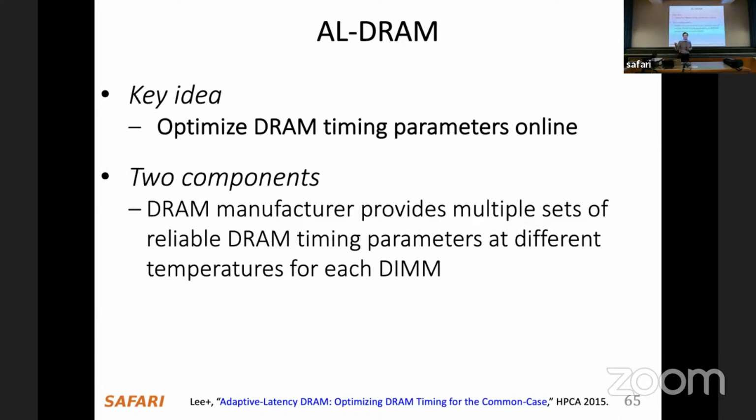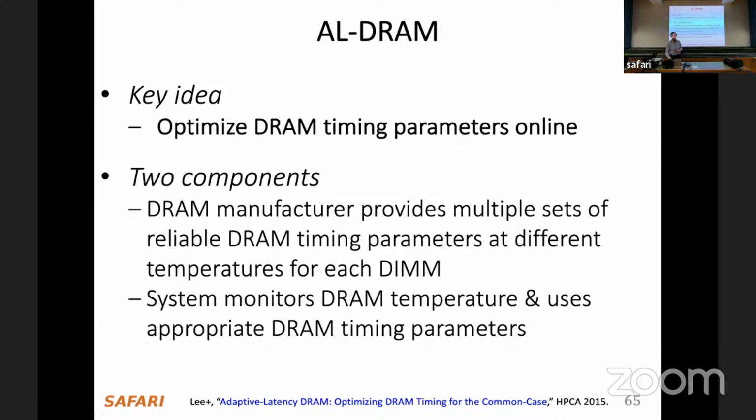We want to optimize the DRAM timing parameters or latencies online. And here, the proposal was to have the DRAM manufacturer provide multiple sets of reliable timing parameters at different temperatures for each module. And the system monitors the DRAM temperature and uses appropriate DRAM timing parameters.